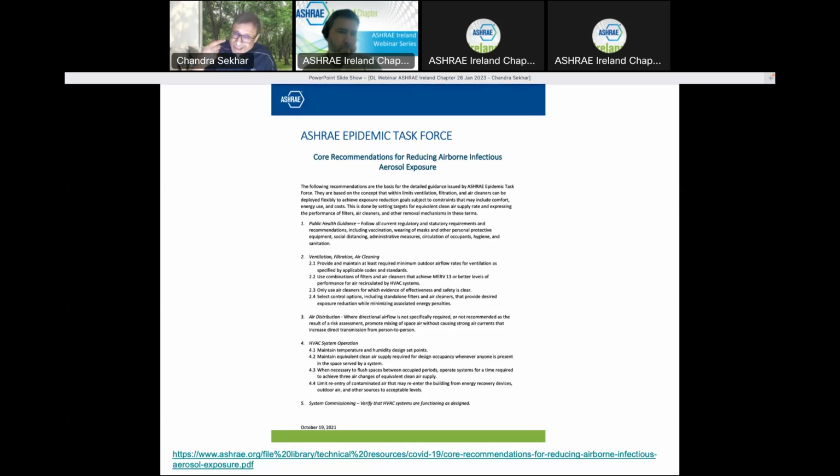I think our understanding of what's happening within the room air movement, the room air distribution, evolved through 2020 and a good part of 2021, to a stage where the advisory could be modified to say you don't have to always have 100% outside air. You need to have an increased level of ventilation with outside air, no doubt about it.